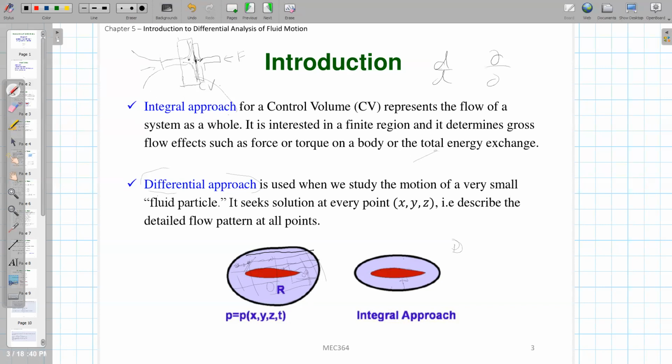We just defined a control volume, right? And then we see how much is moving in, how much is moving out, and how much stays in, and that will be equal to the overall change. That is the way we defined it in the integral approach. We have a control volume with a volume of V here. When we derive the differential form of the governing equation, we will do the same thing. The only difference is that instead of a finite-size control volume V, we will use a differential control volume dV.